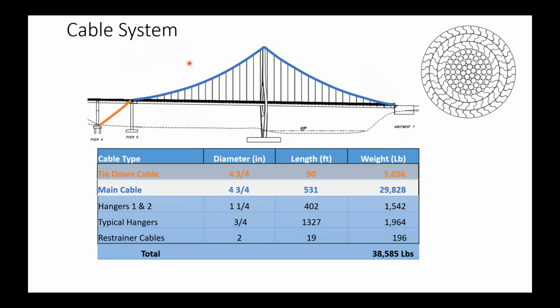So it's a pretty significant heavy element. Then on a bridge like this, on a suspension bridge, quite often you've got connection at the tower. In our case, we did not want to touch the tower here. This was kind of an architectural aesthetic goal to just pass through the eye of the needle here. So these first 4 cables end up taking the bulk of the live load demand on them.